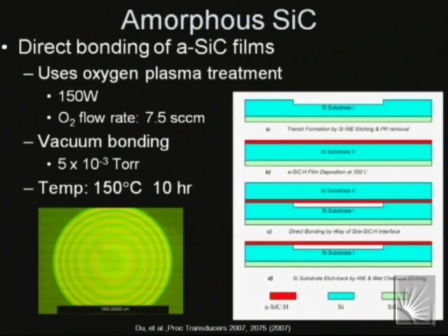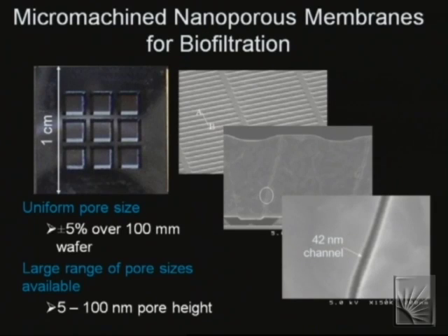And what I mean by short-term is we haven't tested it for years, but that is shown here in this photograph where we have a suspended membrane that is spanning a micromachined circle in the underlying substrate. The rings here are diffraction rings that come about by that membrane deflecting into the cavity by virtue of atmospheric pressure pushing against it. And if there was atmosphere on both sides by way of a leak, you'd see a flat membrane. I have other pictures that show what happens if you don't get the proper stress and things look ugly, but they still join. So we've got a vacuum sealing process.